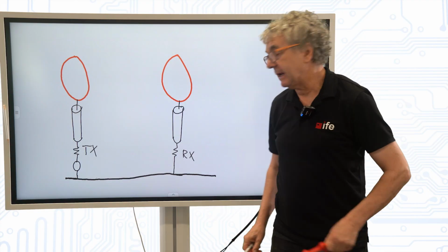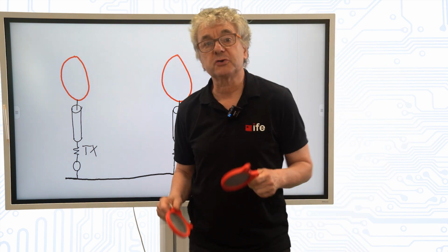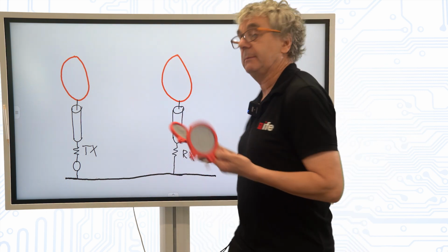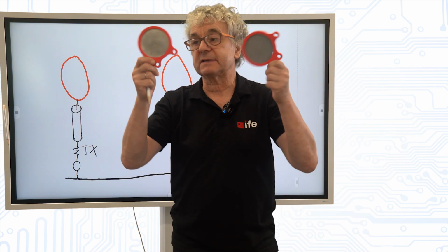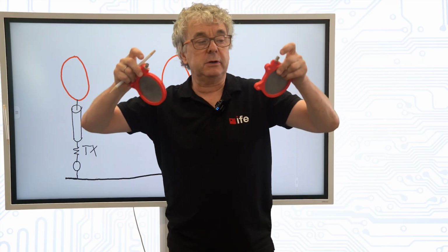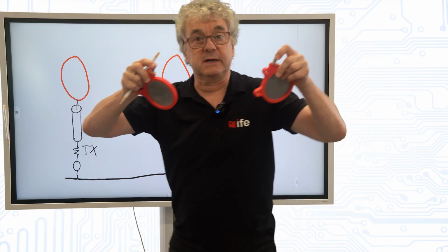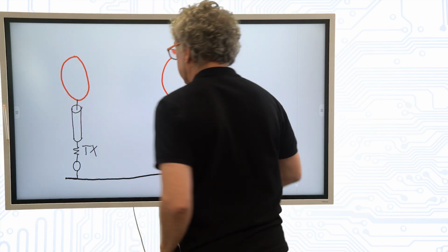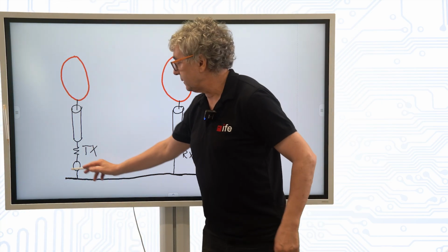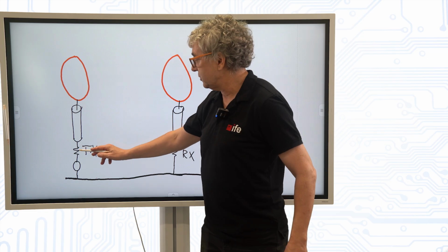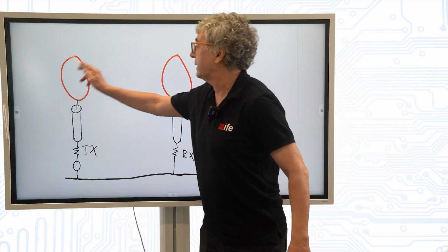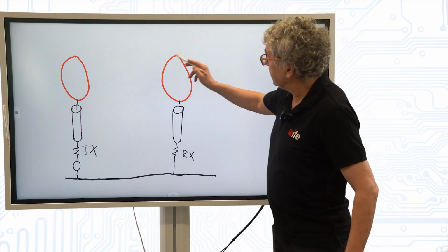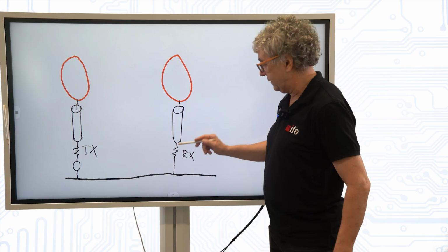Okay, we have just explained or showed you the experiment. Now let me show a little bit on a circuit level some of the background. So we have these two metal discs. They're simply connected to the inner conductor of this coax cable. If you think about this as a circuit, here is the transmitter side of the network analyzer: voltage source 50 ohm, coax cable connected to one of the discs. The other side, the disc connected by coax cable to 50 ohm.